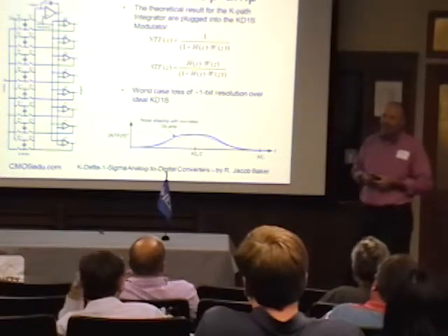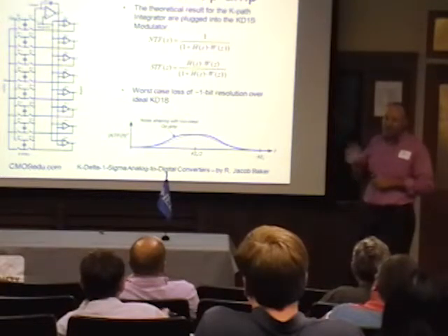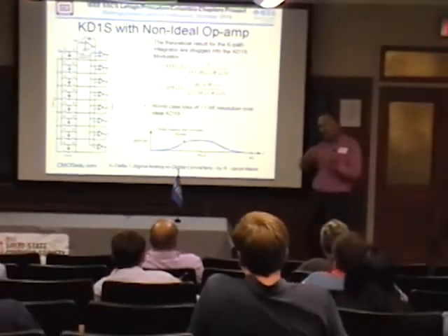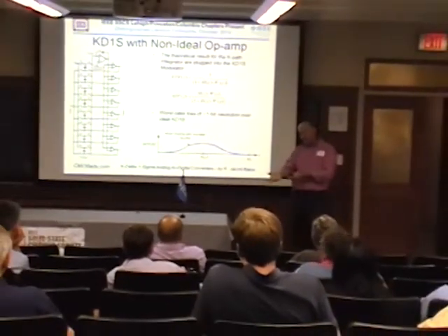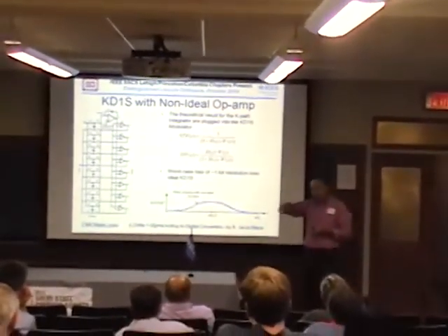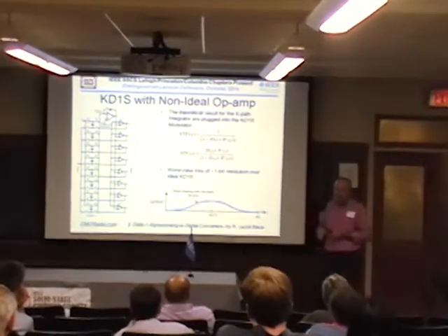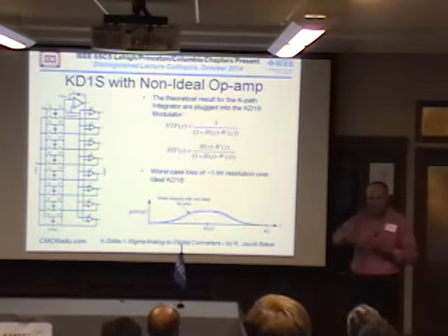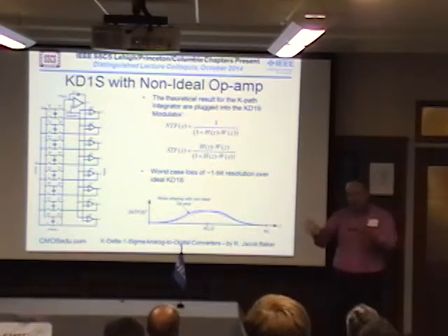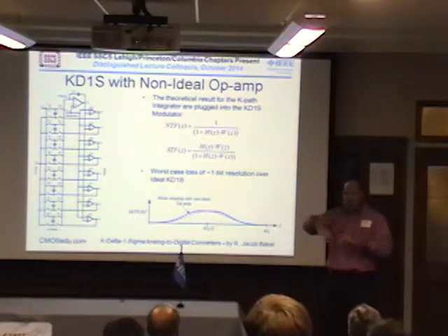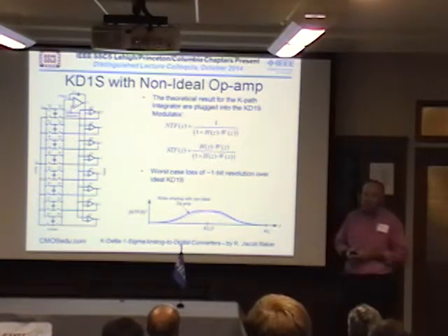I think that if you can generate an asynchronous clock for a SerDes application, which is not related to your input signal, but generates the phases of the clock that you need, you could actually do it with a ring oscillator and just tap off. Of course, there are issues with the phase noise of the ring oscillator, but assuming those aren't a problem, you just tap off and asynchronously bring the signal in, look at the digital data clocked out, and use your DSP to reconstruct. Maybe you can feed back a signal to adjust or modulate the amplitude or something like that, where it can be really simple.